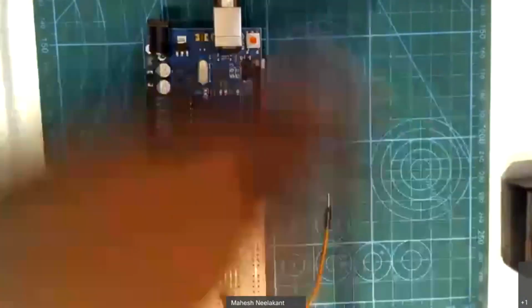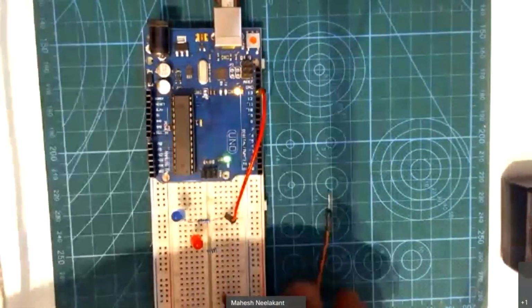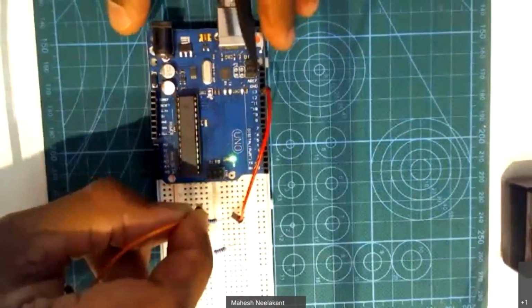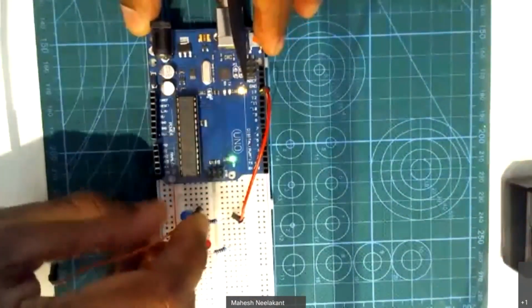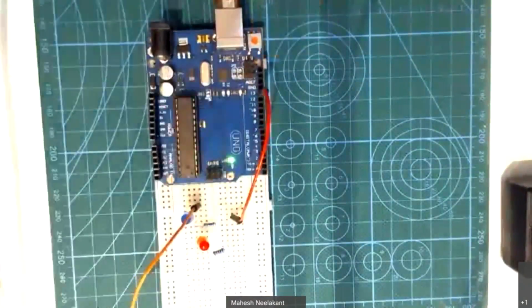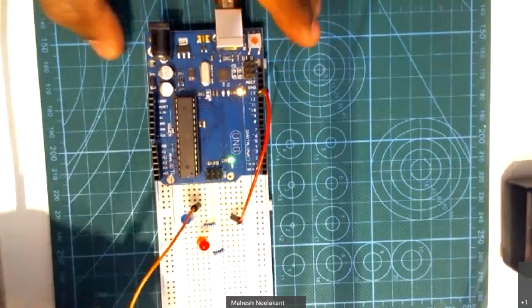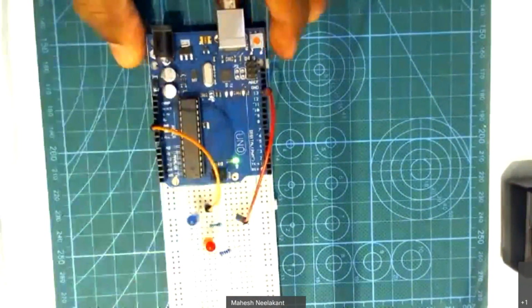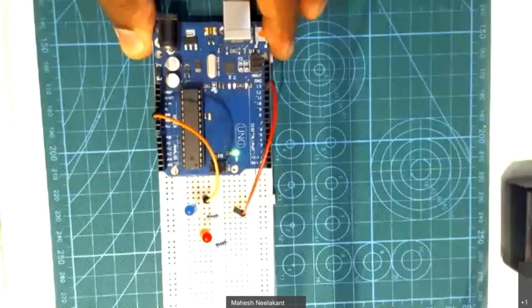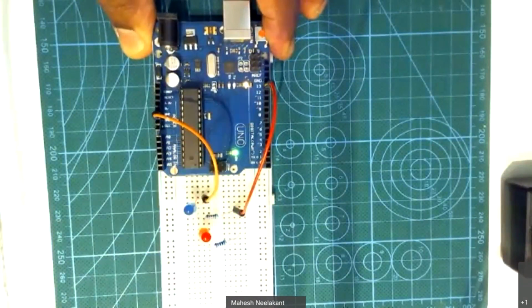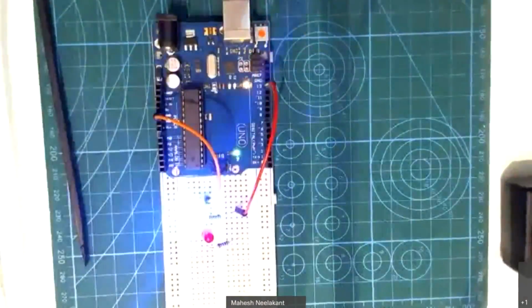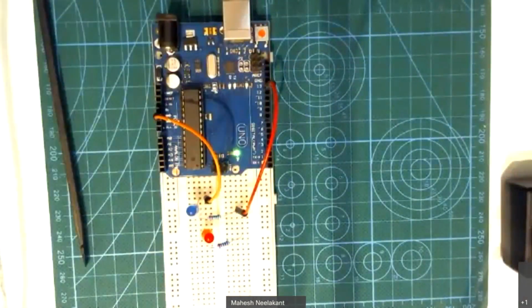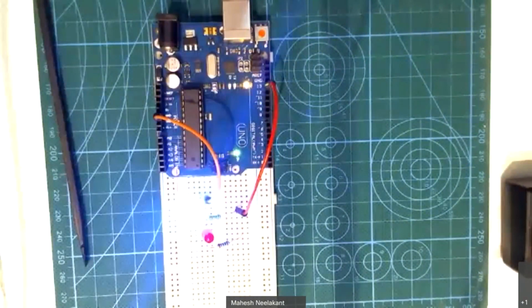The last thing to do is to connect up the ground. And so I'm going to take another wire and connect this up. If you know anything about circuits, the reason it's called a circuit is literally it's a loop. Like a car circuit or anything like that, you have to close the loop. So I'm bringing that back up and I'm going to connect it to ground. I happen to already be running the code, and that's why it already started blinking. Now, the other two are going to be there in just a minute, and I'll explain why in a second. So I'm going to stop, switch to presenting my screen again.